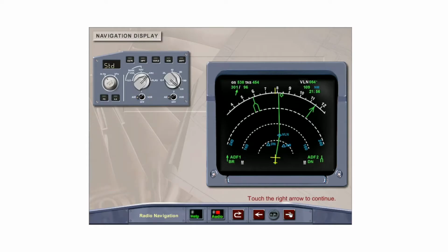With ADF selected on the EFIS control panel, the navigation display will display ADF-1 as a single green course pointer and ADF-2 as a double green course pointer. The NDB station information is displayed in the bottom corners of the navigation display. The information includes the associated bearing pointer shape, the station identification code if the station is identified, or the frequency if the station is not identified, and as with the VORs, if the station was tuned automatically, manually, or through the radio management panel.